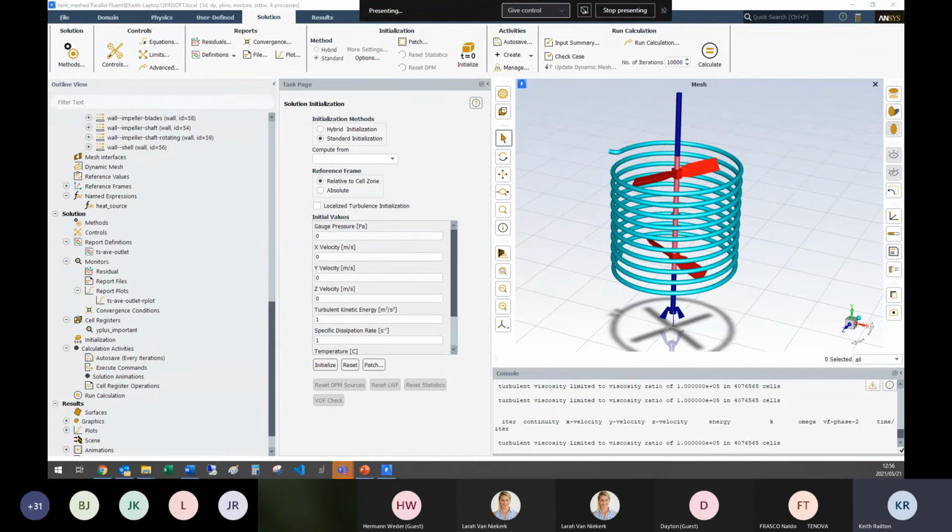All right, so then also recommended a couple of monitor points within the 3D zone. Yeah, there's definitely the more monitor points you have, the better. One important thing is monitor points can be used for visualization purposes only. And I think it's very important to not judge your convergence only on residuals, but look at both your residuals and the monitors of interest.